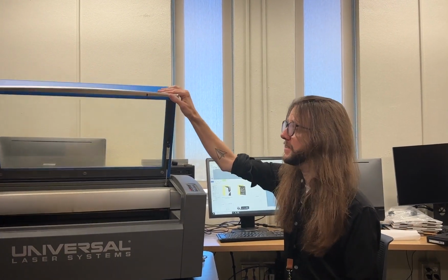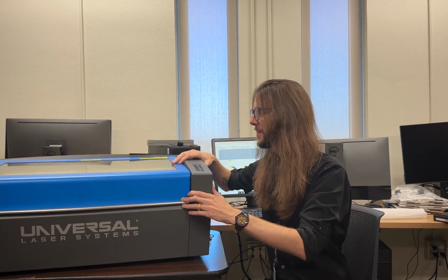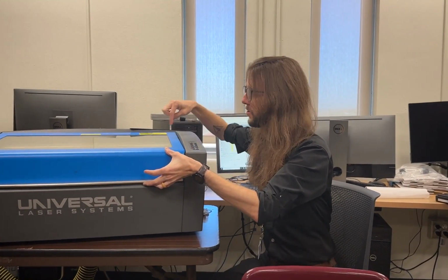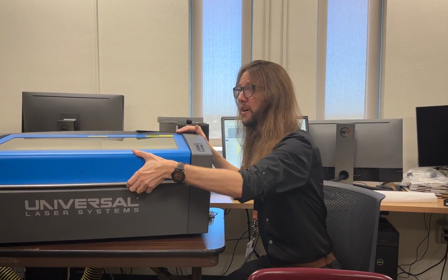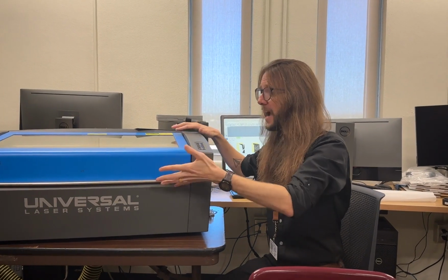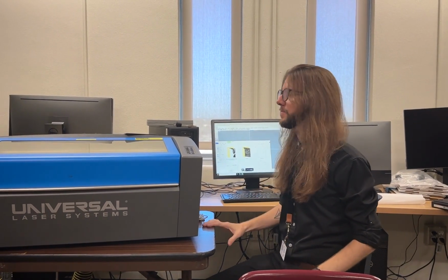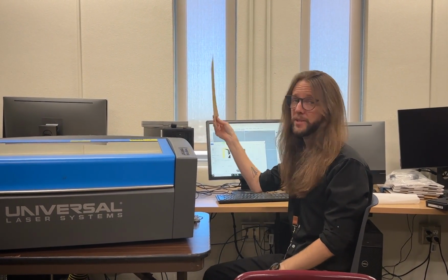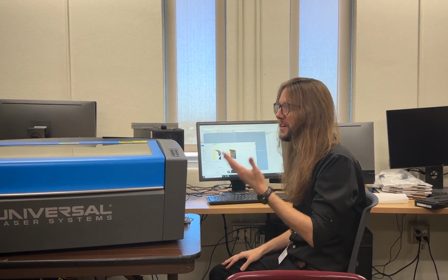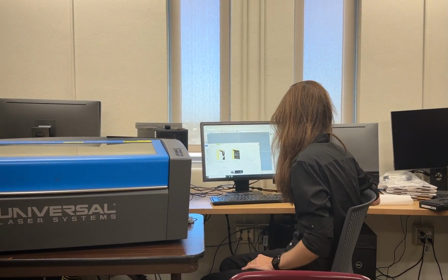Basic settings, you really can't hurt yourself with this machine. I guess you can if you just started to fool with it, but technically, as soon as you open this, the laser will cut off. So even if you're starting to cut and you see a fire, immediately open it. I know that sounds counterintuitive, but actually it's going to cut the laser as soon as you do that, and of course immediately cut the fire as well. So again, fire is an issue because we cut paper products. So keep that in mind. Same with wood products, plastic products. You can actually cut leather on it. It smells awful, but leather is flammable too.